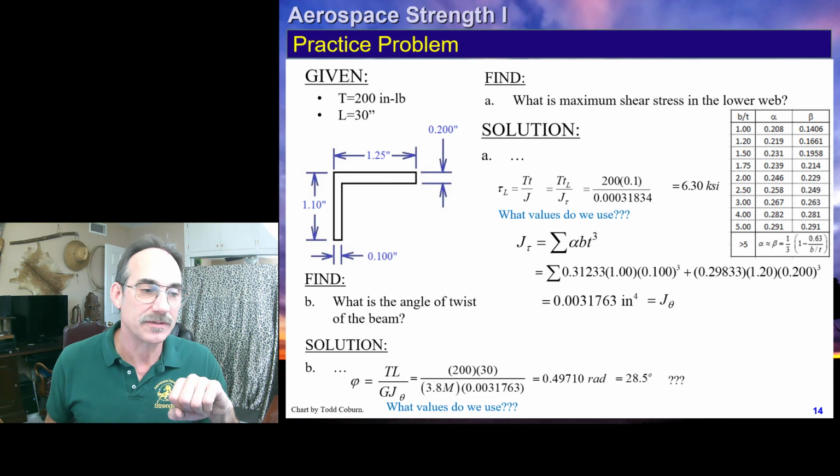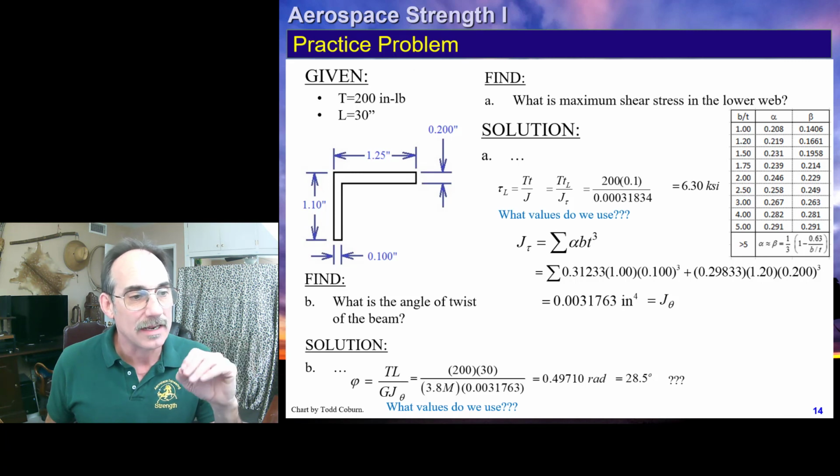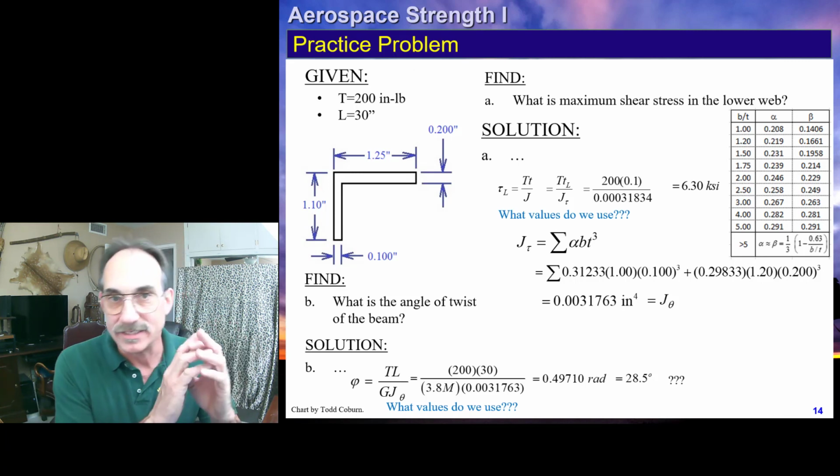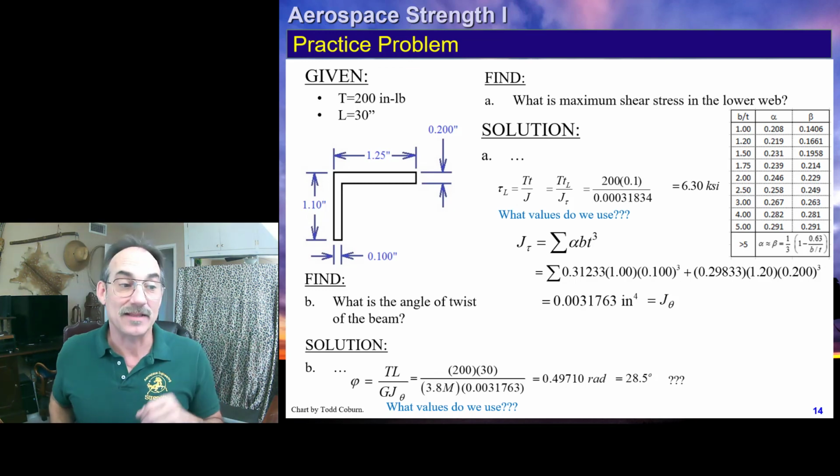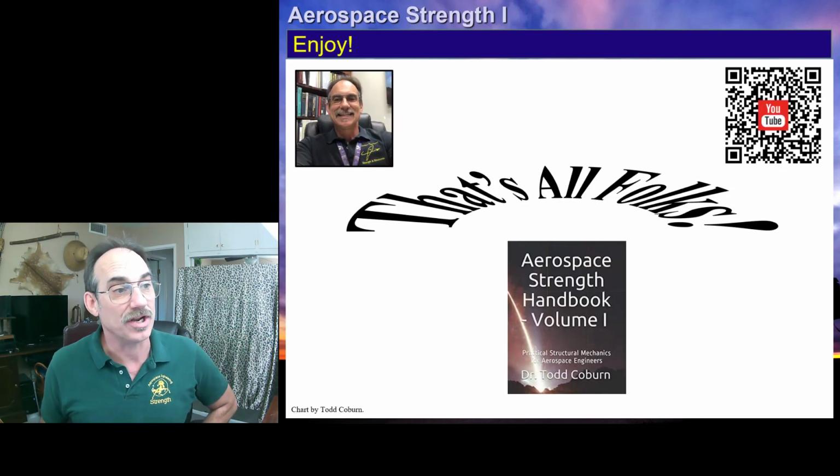That's how it works. You'll notice here this angle, 28.5 degrees. This means under this little torque, this thing rotates 28 degrees. You notice that means it's so flimsy, it probably is not going to pick this up unless there's nowhere else for that torsion to go.